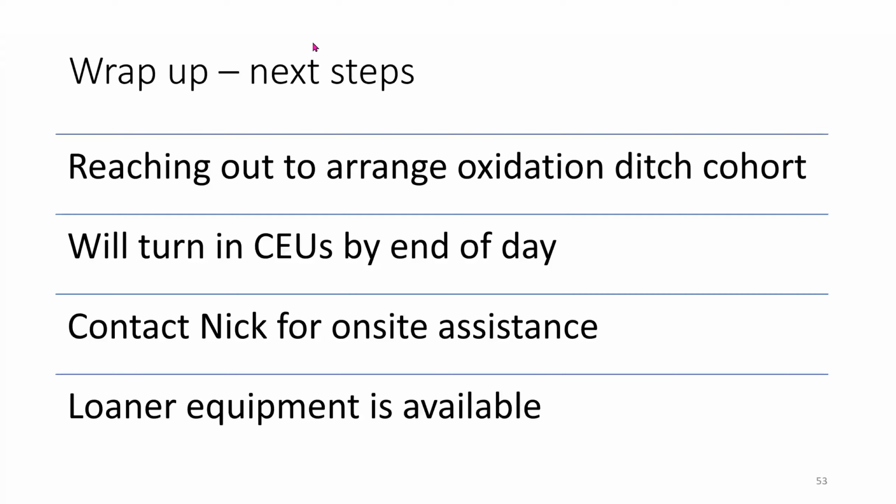So the first question, Grant, is the ORP one? Yeah, let me jump on that. That's a great question. And you kind of kick it back at people to think about. So ORP measures how actively organisms are using oxygen. Positive numbers is how actively they're, let's say, breathing free dissolved oxygen. The negative numbers is how hard they're working to break molecular bonds to, again, I'll use the word breathe, to breathe bound up oxygen, like off of nitrates.